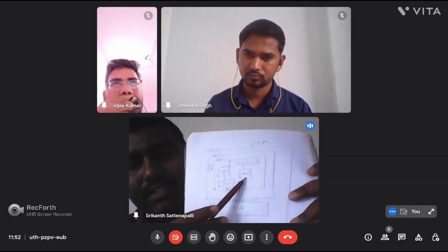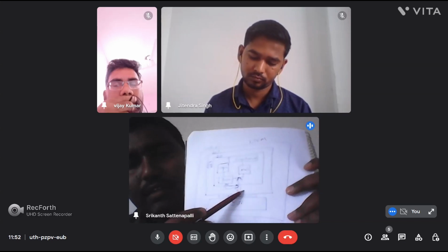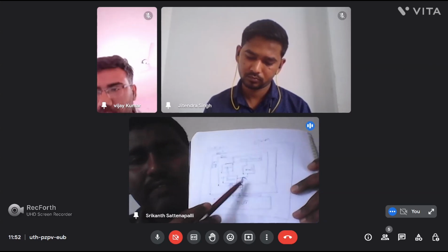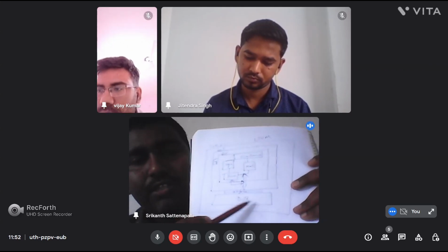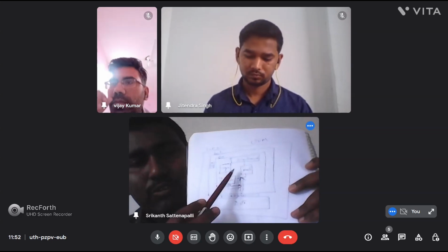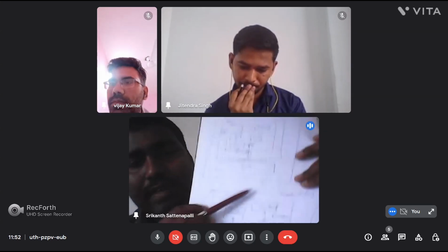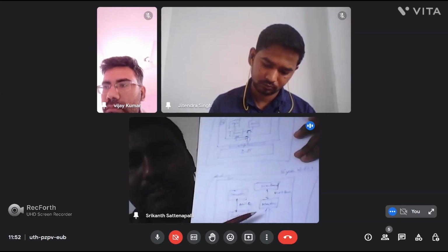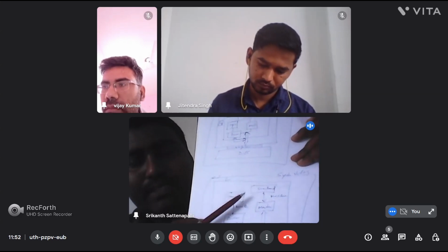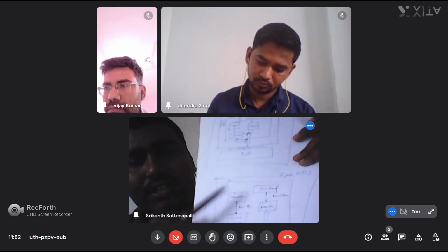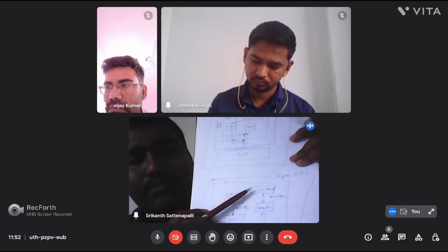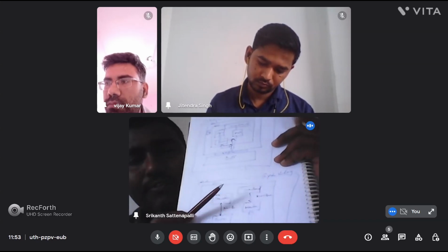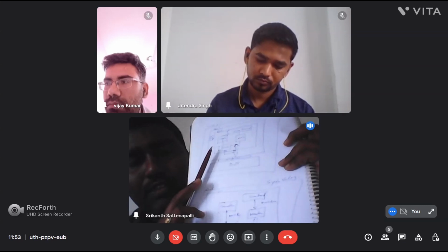Okay. In UVM we are having the sequencer, driver and monitor to the scoreboard, and we are connecting the DUT through the interface. So the driver can drive the signal to the DUT. Then those signals will be collected from the monitor and we are checking in the scoreboard. Similarly in the SV testbench, in place of the sequencer we are having the generator and driver. Here the connection will be made through the mailbox, and with the DUT the interface is the same as in UVM.